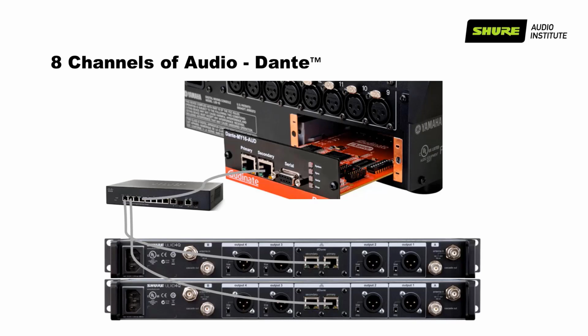So it's less cabling, and hum, buzz, and all those other extraneous noises that can bedevil an analog microphone signal or analog audio signal, period, become non-existent when you've got it on a network. Now all you're worried about is things like packet loss. As long as your network is robust enough, you don't lose packets and don't need to worry about too much error correction, and everything sounds good. It can sometimes solve a lot of problems. And again, this is all using standard Ethernet hardware.